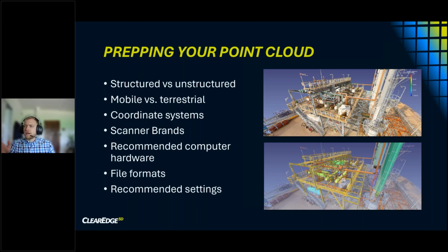So, enough about that. We'll keep going into the coordinate system. This one's a big one, and anyone who's actually done scan-to-BIM projects will know that getting coordinate systems wrong is very painful. That's a bad time. Just like any other workflow, really thinking about what coordinate system you want to be working in and need to be working in is very important to do before you start working, in any process. That's true regardless of your workflow. You always have to make sure you're in the right coordinate system, and that's still true for EdgeWise.